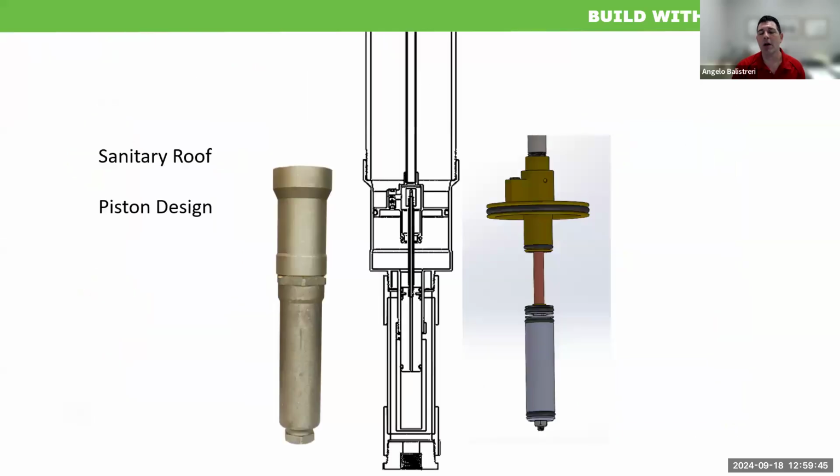We took care of that with removing the Venturi side, and we do a piston water displacement. So our reservoir sits here. This little piece here is the water inlet piece, and then the reservoir sits right here, which is this section right here. And this piston is what you're seeing right here. The water sits in here, and with our design, when you lift the handle, it drives this piston down, and that water displacement immediately comes out. In fact, the water in the reservoir will be displaced before the fresh water even comes in.